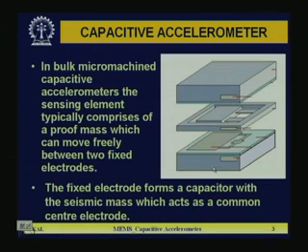In the bottom piece, a fixed parallel plate electrode is configured, and you can take the contact from the side wall, or some bond pads are ejected at the outside from where you can take external connection. Similarly, at the top fixed electrode also there is a metallized plane which acts as electrode. So, the top fixed electrode and bottom fixed electrode will form capacitances with the middle sensing element.